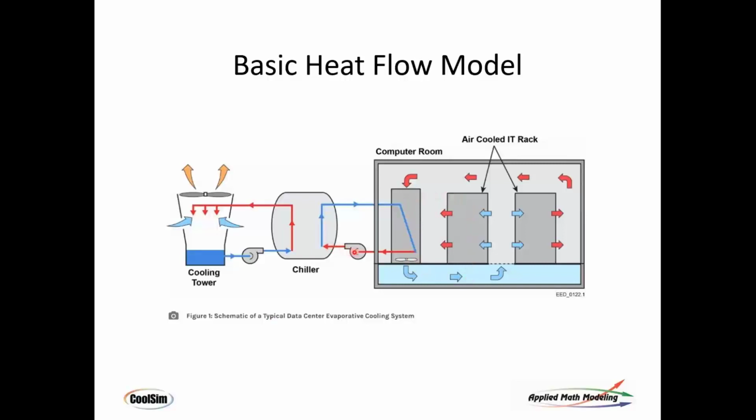What happens on the outside is you have the hot liquid, usually water or glycol, coming up and through the chiller. Inside the chiller, you have compression, same thing as before with a DX unit. You've got a gas in there being compressed to a high temperature, being dumped and being expanded so that the heat transfer can take place between hot and cold to pump the heat out, done through shaft power. So you put shaft power in there, spin it, it does compression or lift. That gets things hot. You dump it, typical Rankine cycle, that's how you do it.